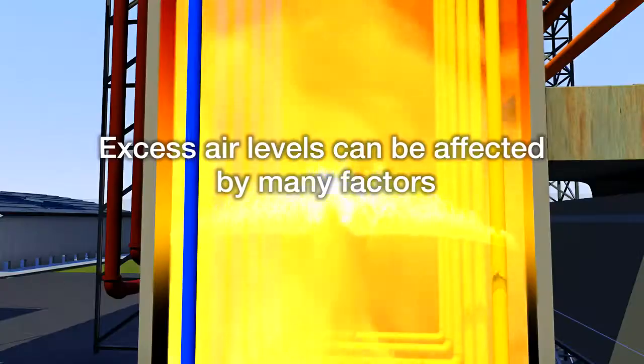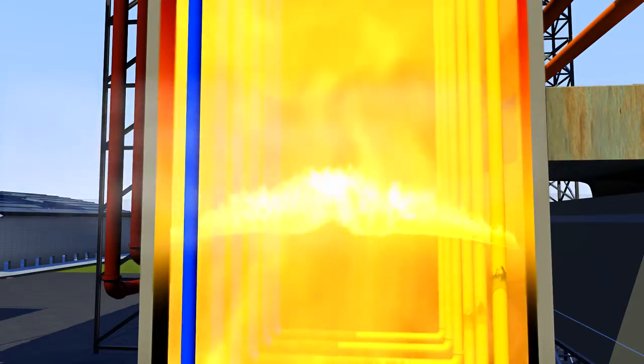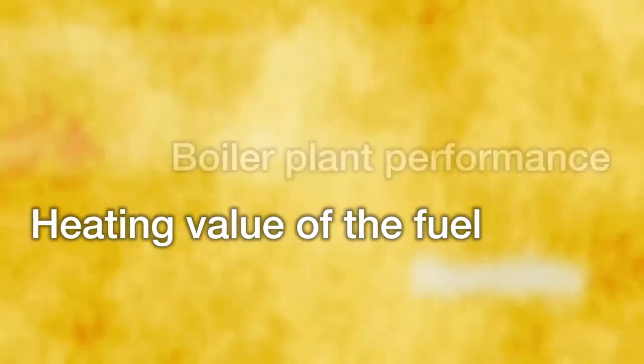However, maintaining the correct level of excess air for combustion can be complicated by variations in the fuel and the air. Factors include atmospheric pressure and humidity, changes in the heating value of the fuel, and the performance of the boiler plant itself.